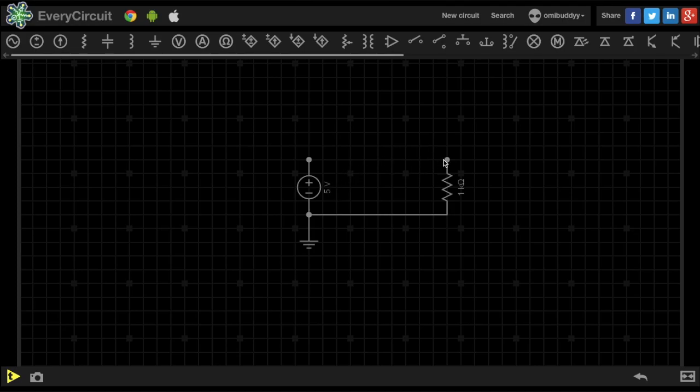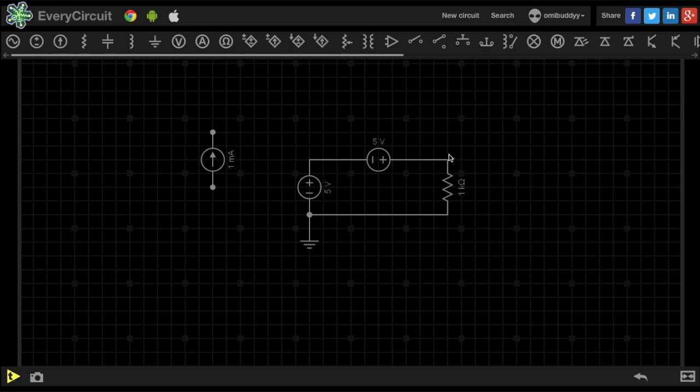The first thing that comes to my mind after this is a voltage source. For example, if we want a gain of 2 and the input voltage is 1 volt, then the black box should add 1 more volt over the existing 1 volt of input so that we can get an output of 2 volts. We will think later about whether the use of a current source is possible or not. As of now, let's stick to voltage sources. Let's put a voltage source of 5 volts and see if we can get 10 volts at the output. As seen, now we are getting an output of 10 volts when the input is at 5 volts. So we have achieved gain.